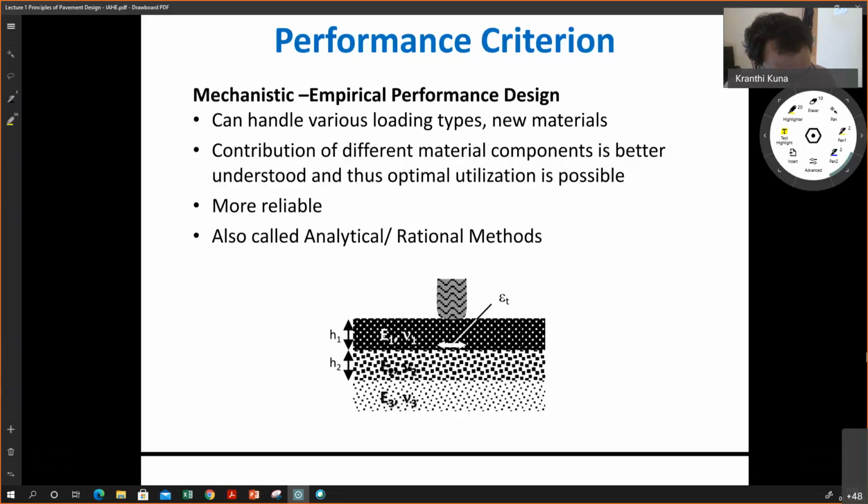I'll be repeating this towards the end as well. Pavement design is like any other design, for example any structure: we take seed values for the dimensions of a structure. Similarly, we take seed thicknesses. We start with certain thicknesses and run the analysis. If you are analyzing a structure in some FEM tool like STAAD Pro, ANSYS or Abaqus, the output is stress, strain, and deflection.